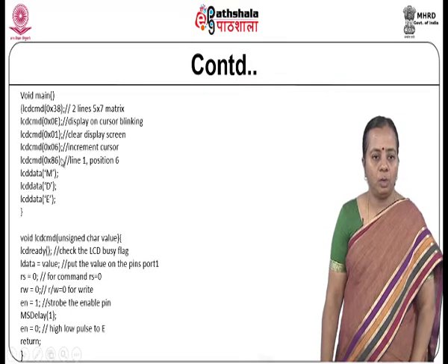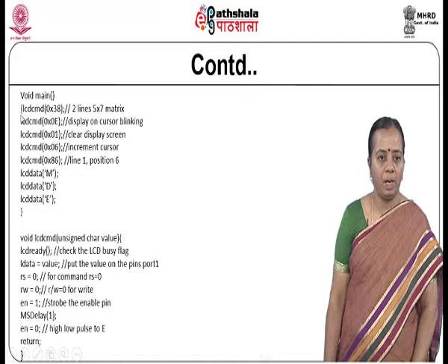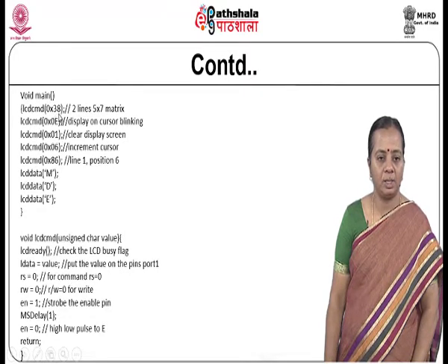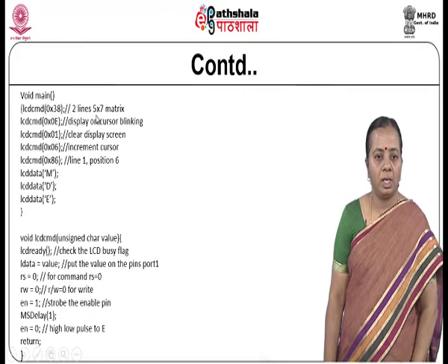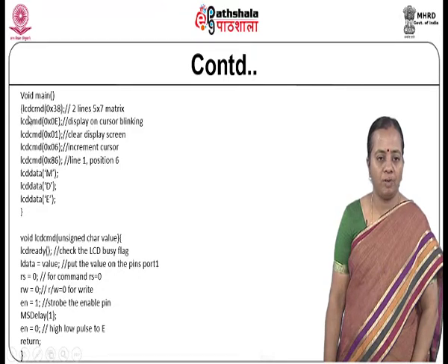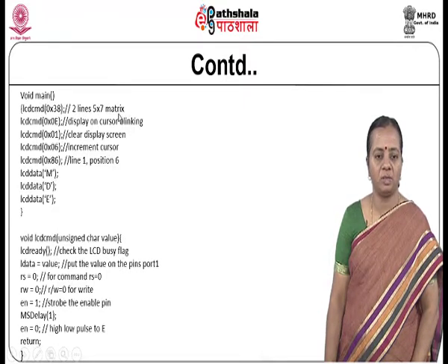Now, in void main, we call LCD_CMD with 0x38, which informs the LCD of 2 lines and a 5 by 7 matrix.